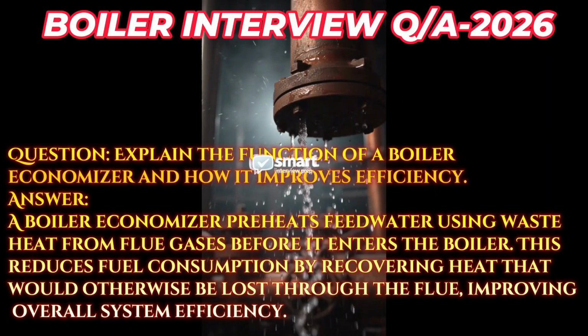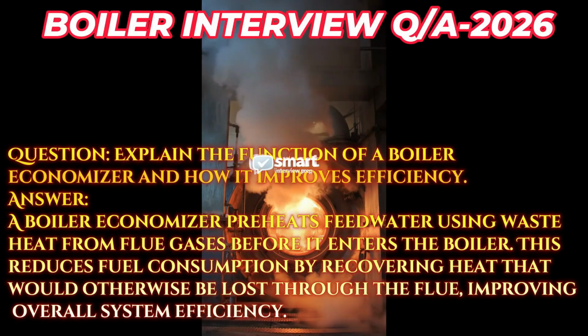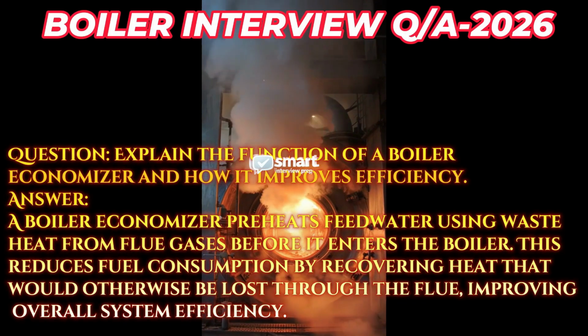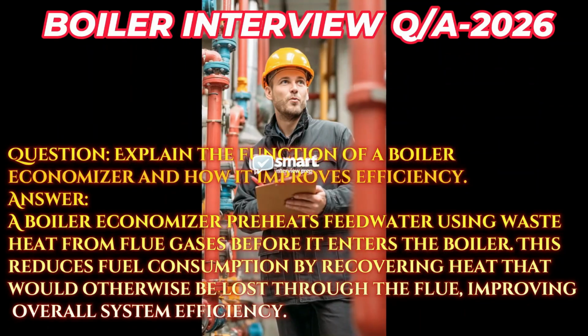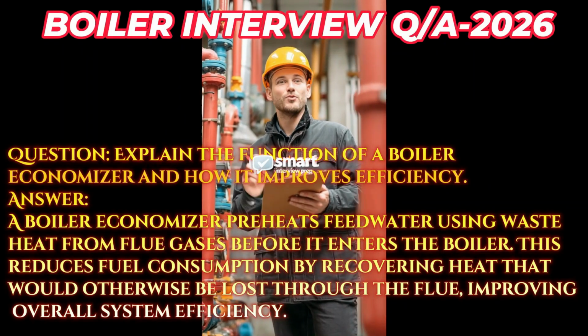Question: explain the function of a boiler economizer and how it improves efficiency. Answer: a boiler economizer preheats feedwater using waste heat from flue gases before it enters the boiler. This reduces fuel consumption by recovering heat that would otherwise be lost through the flue, improving overall system efficiency.